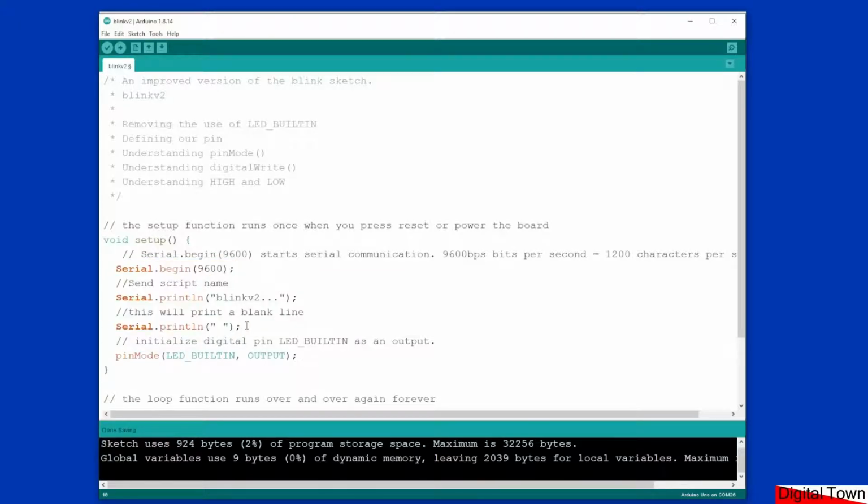I've had a few identical Arduino Unos on my desk. I've been loading them with different sets of code, and now and again it's got to the point where I've thought, hang on, which sketch is on which Arduino? So by just plugging them in and opening the serial monitor, I can find out which Arduino is which, which is why I continue to have this sort of structure whenever I write a sketch.